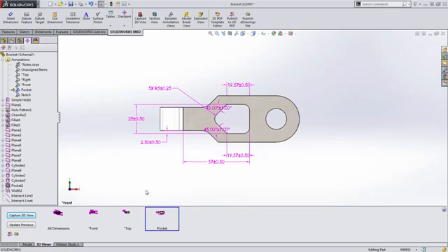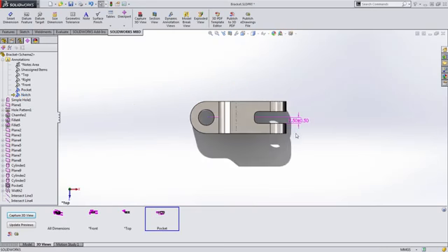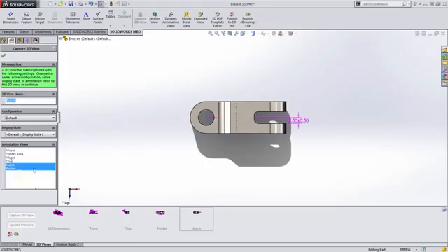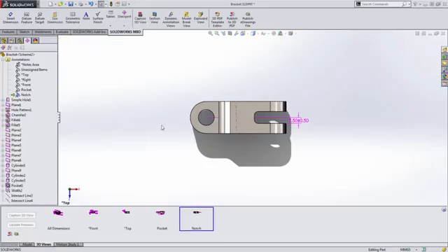There's one more view we want to add. We want to capture the information for that new notch we just created. So let's go ahead and activate and orientate to that notch view, and let's choose to capture this 3D view. Now in this case we're going to choose only the notch annotation view and press OK.